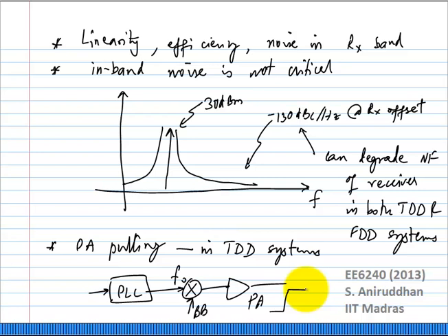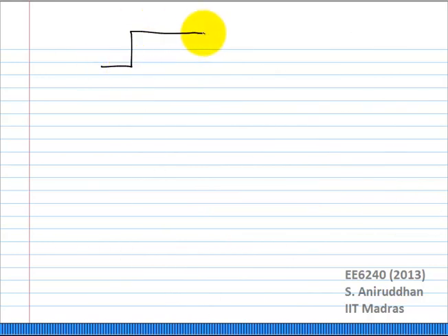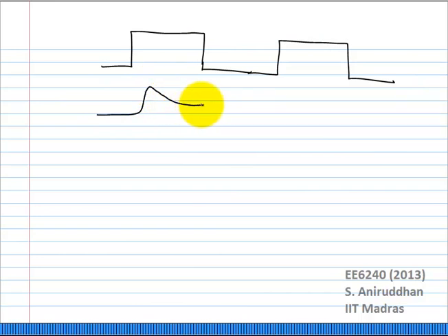The classic sign of this will be, you have a turn on and turn off time, and what you'll find is, if you look at during this turn on period, let us say it looks like this, you can actually plot the EVM as a function of time. Okay? And what you may find is that the EVM may look like this. This is your steady state EVM. Okay?